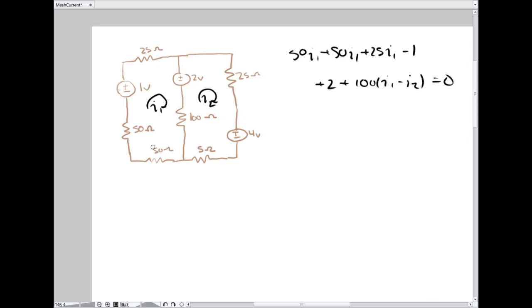As you would notice, you could just combine these 3 resistors in series beforehand. Notice how rearranging the position of the resistors and this voltage source does not change the mesh equation, therefore it doesn't change the solution for the mesh currents. It will change, of course, the node voltages because it rearranges the nodes. But it won't change the voltage drop across each individual component. So you can always rearrange the voltages afterward.